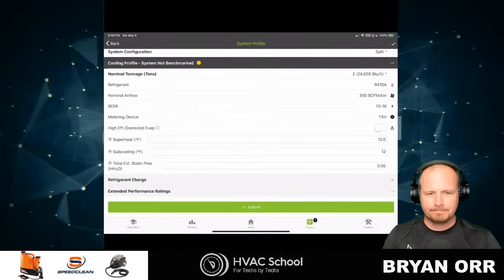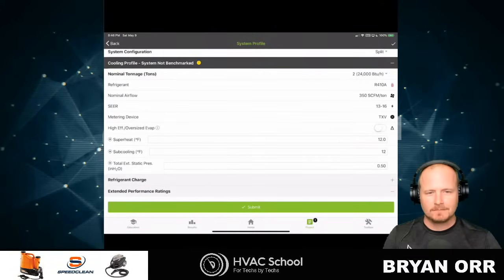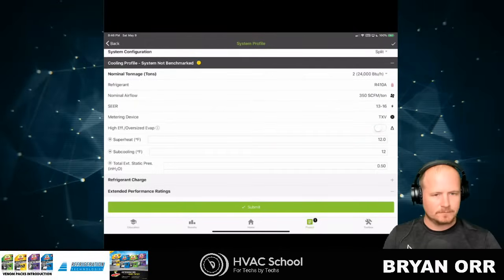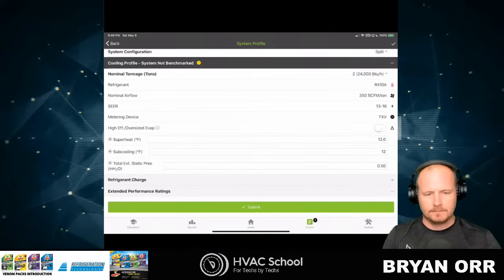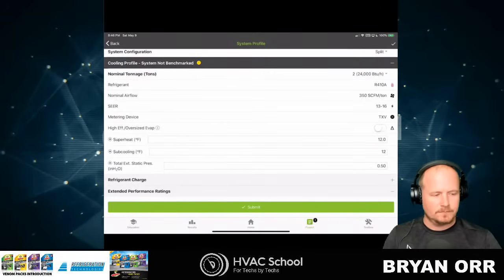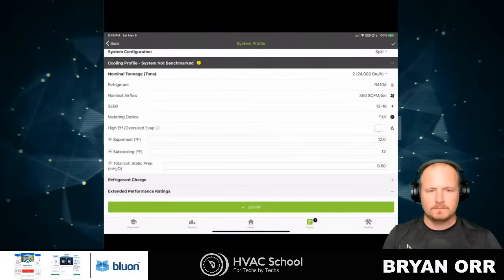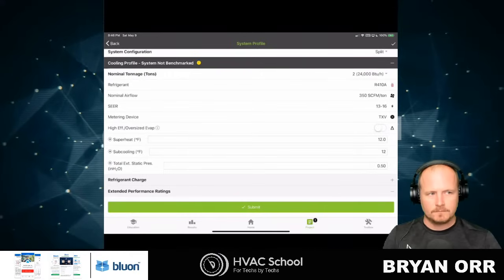And then another thing people sometimes mess up is they capture data and they don't clear it. So there's capture buttons on some of the screens. Like if you got out of probe range, I just had a guy call me yesterday. He's like, it's not reading right. It's different. And I'm like, okay, go into outdoor measurements and hit clear. And he goes, oh, that fixed it. Okay, I forgot I captured those measurements. So there's a couple little things you got to learn. But once you're past those, you're good to go.